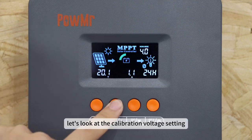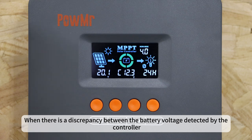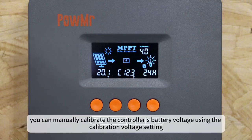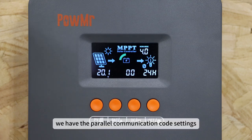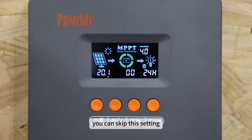First, let's look at the calibration voltage setting. When there is a discrepancy between the battery voltage detected by the controller and the voltage measured by a multimeter, you can manually calibrate the controller's battery voltage using the calibration voltage setting. Next, we have the parallel communication code settings. If you are not using parallel operation, you can skip this setting.